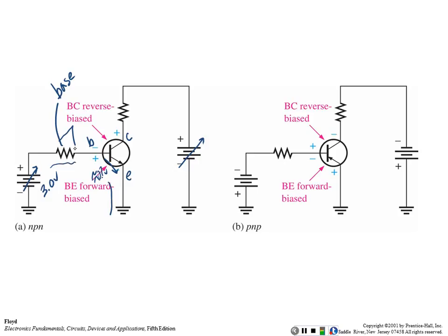So the resistor's not dropping 0.7, the transistor is dropping 0.7. What's the resistor dropping? 2.3 volts. Are you okay there? Approximately. We understand that it's not exact, but it's close enough for us to calculate, right?